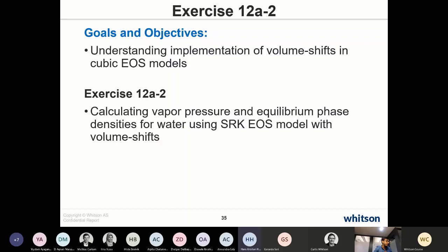Yes, Hans? I just have a question here. Maybe that's been a little confused, but in PVTsim they have something they call temperature-dependent volume shift. I don't know if you're going to cover that, but I have been told that if you have a problem when you tune an equation of state and you have problem matching the reservoir density and the stock tank oil density, you can use that. And I have seen that if you're dealing with a very heavy oil, you have to use that.